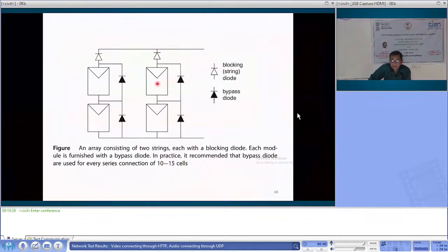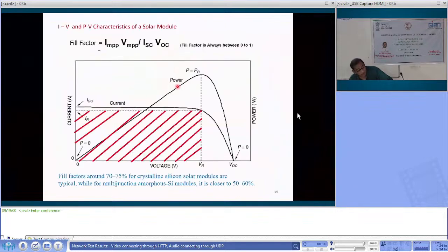So I guided one MTech student and he presented a paper at NIT Bhopal, this student conference, on the partial shading conditions of this PV module, and he considered several cases and then simulated like this. तो ये blocking diode जो दिखाया है, ये dark वाला नहीं, दूसरा, that has to block, because if you are connecting through a converter to charge a battery, you don't want reverse current, उसको block करना है, इसका नाम blocking रख दिया. Bypass means the solar panel is shaded, then you should have diversion, so a bypass route is there. So that is the basic concept and their functions are important.